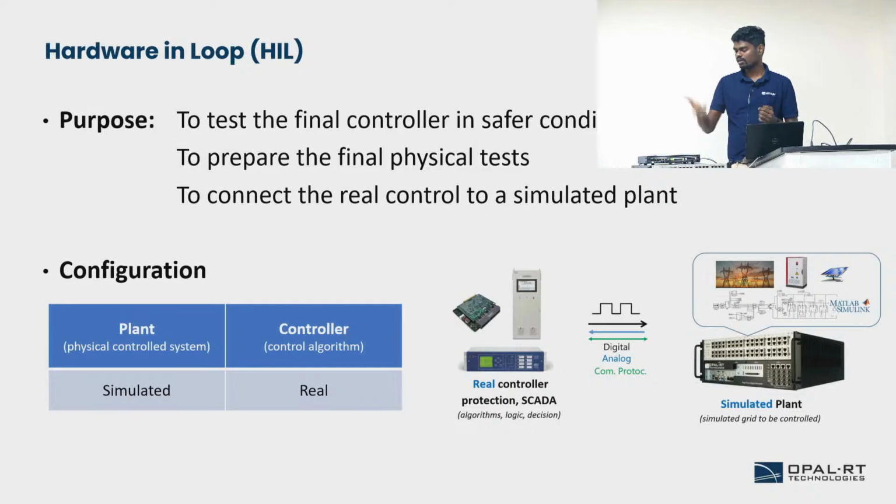You can test it for a lot of other scenarios like different adverse load conditions or some fault conditions. You can test your controller, and then you can go for the final hardware implementation. So this is hardware in loop.